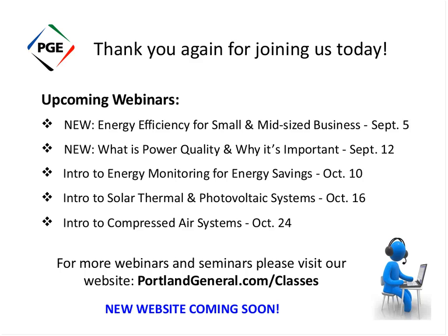So, with regards to dimming, how does CRI change? Okay, when you dim incandescent, the CRI is actually not going to change, but the color temperature will. When you dim incandescent, it goes much warmer. When you dim most LEDs, they either don't change or sometimes they could go a little bit cooler.